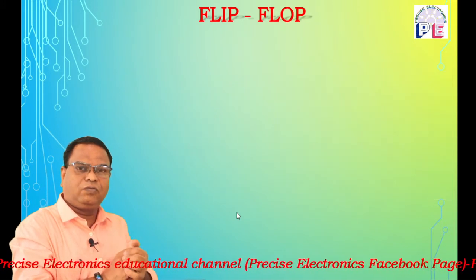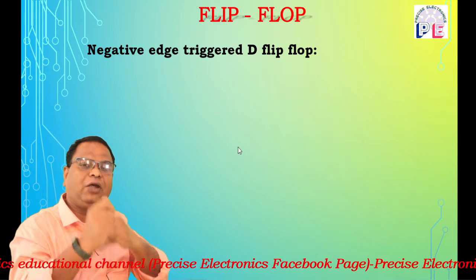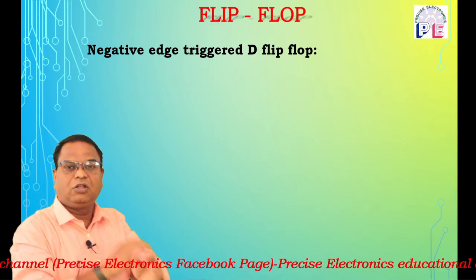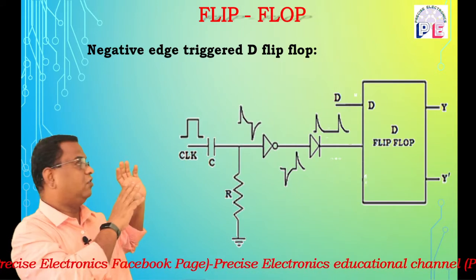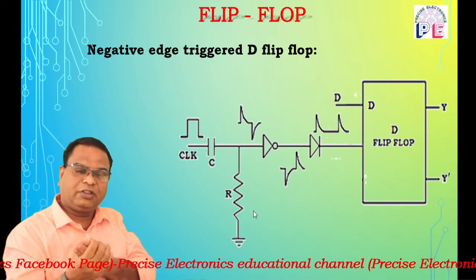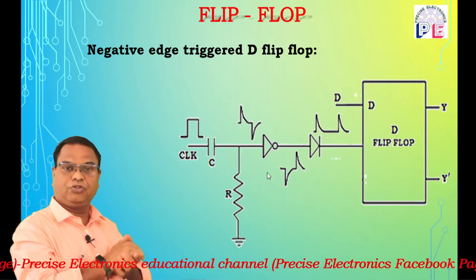The next flip-flop is the negative edge triggered D flip-flop. In this case, the negative edge is applied to the flip-flop, and the transition of state occurs at the negative edge. This flip-flop is known as a negative edge triggered flip-flop. The logic diagram of the negative edge triggered D flip-flop is now going to display on your screen. The same circuits, that is a capacitor and resistor forming a differentiator, are used, then a diode is used, but between the differentiator circuit and the diode, an inverter, that is a NOT gate, is used.